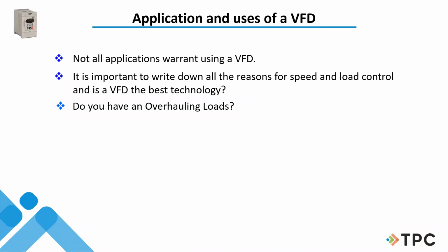So if I'm going to slow this big load down, I better know how much I've got so that I can be ready for it. So I can put braking resistors in. There's a lot of options if you look in your manual for your drives. A lot of things I can buy that help me with this load, that get rid of heat, get rid of some of that current, because if your drive gets hot, it's going to kick out. That's all there is to it.